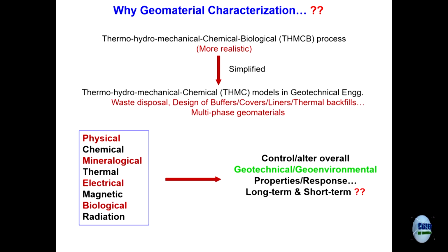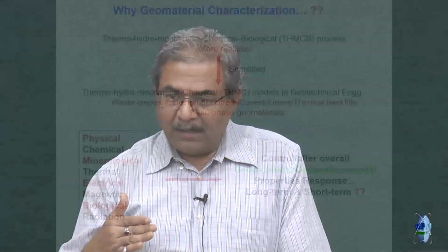So, when an earthquake comes, the structure does not have much time to understand how it has to behave, all right. The impact is so quick, and whatever happens is in a fraction of seconds or in a few seconds. So, this is a quick, undrained system. The material does not have much chance to expel or dissipate the pore pressures, all right. And the long term is a slow process where the drainage occurs.